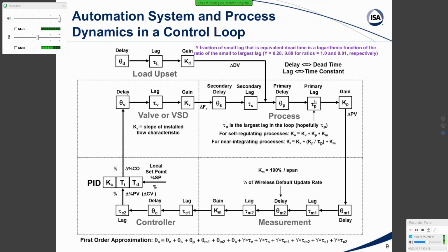In the literature, typically when they develop internal model control and even lambda tuning, the idea was that this time constant was not that much bigger than the total dead time. And they didn't put the disturbance here, but they put the disturbance on the output. Now, if this time constant is not too large compared to the dead time, it doesn't really matter where it is. But it turns out for the type of processes, particularly that I was involved with, the disturbance really comes at the input of the process.